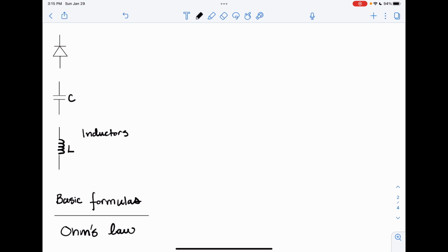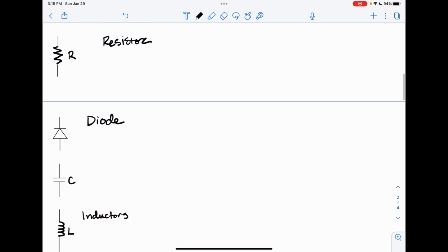Next up is an interesting one, the diode. The diode is not like a resistor in the sense that it simply creates a current draw. The diode limits the direction of current flow, and it does have some potential difference across it, but we'll get to that when we start talking about the constant voltage drop model in semiconductors. Diodes are quite useful in power applications, as we often like to use them to build rectifiers. So keep that in the back of your mind.